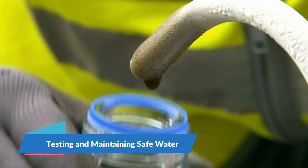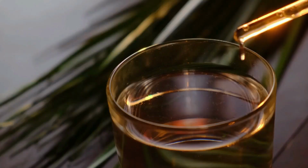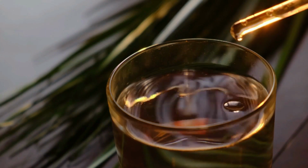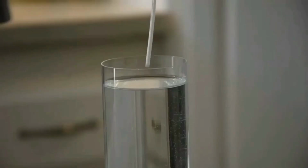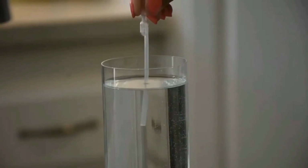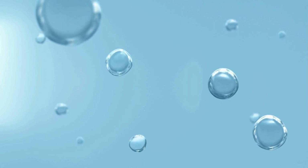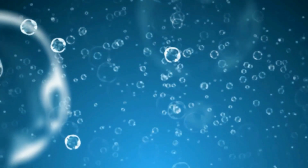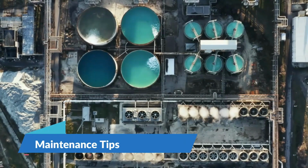Testing and maintaining safe water. Number 1. Testing kits. Importance of testing. Regularly test your water to ensure that the chemical levels are safe and effective. Test kits for chlorine and other chemicals are readily available and easy to use. Frequency of testing. Testing frequency should increase with the volume of water purified and the sensitivity of household members to contaminants.